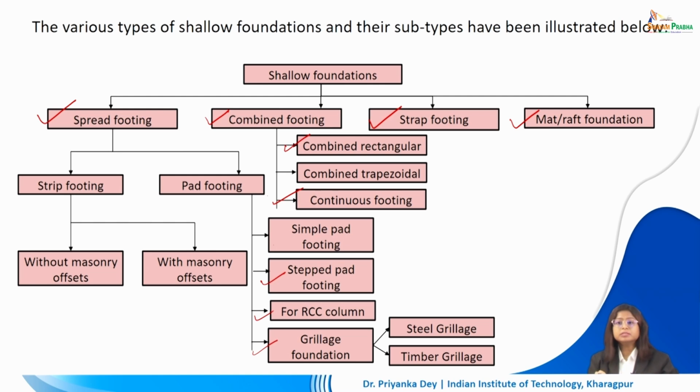Now, we do this when the bearing capacity of the soil is very low and the size of the footings are coming pretty high, or it may so happen that they are very closely spaced together. So, it's more economical for us to go for a foundation for the entire thing. In general, we can see that in the staircase or the lift lobby portion of a building, maybe there is isolated pad footing for most of the columns, but for the lift portion, because the columns are coming pretty close to each other, we can go for the raft or mat.